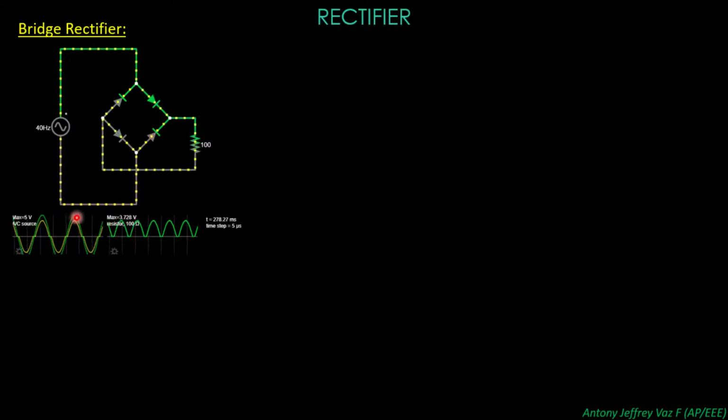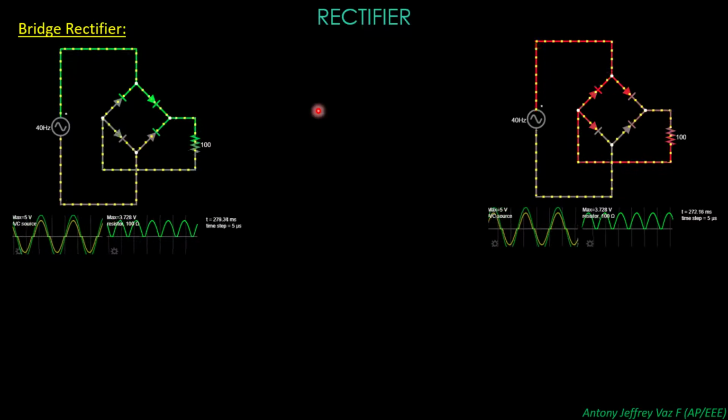So in the case of the positive peak, the diodes D1 and D2 will be conducting because of forward bias, whereas the diodes D3 and D4 are in reverse biased condition. So D3 and D4 will not conduct, D1 and D2 will conduct during the forward biased supply. In the second stage, you will see the negative voltage being applied. When the negative voltage is applied, you can see the electrons start to flow from this end into this.